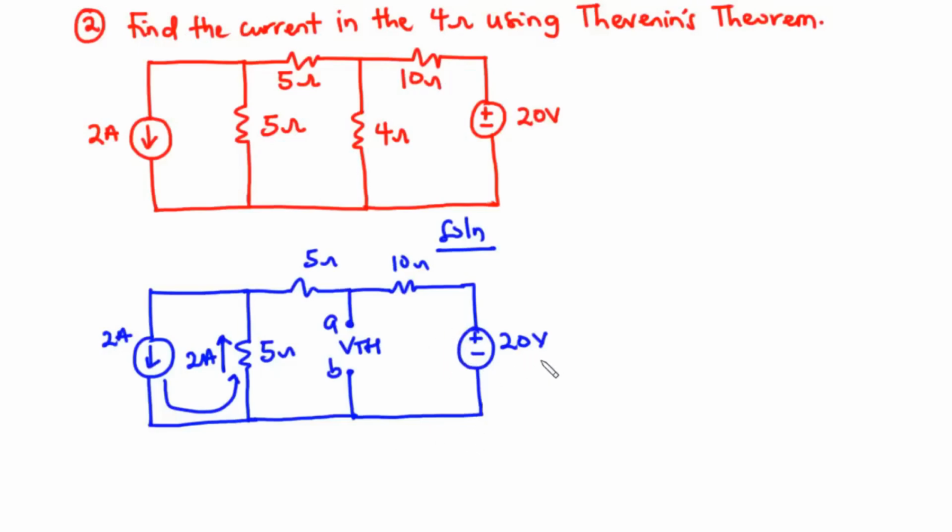Let's move ahead and consider this particular loop. For this loop, this 24 volt source is going to drive current in the anticlockwise direction through this loop. So considering the conventional flow of current, we have current moving in this direction, that is the anticlockwise direction, through these 3 resistors and then returning to the negative terminal of this voltage source. Now let's call the current driven by this voltage source I.